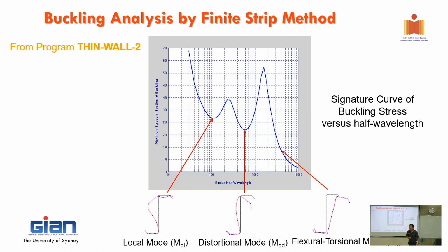FOC, critical buckling stress. Is that the local buckling stress? Yes, so in this case, it is equal to the local buckling stress. You're asking whether this local buckling stress is similar to that? It depends upon the length. Yes.